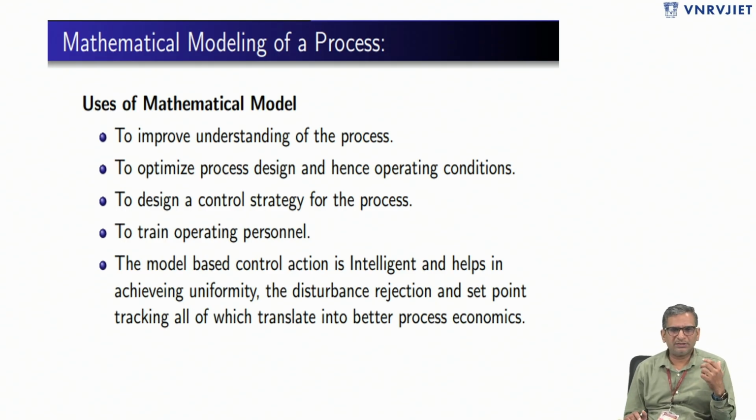In addition to that, once I have a mathematical model, I can use it for simulation purposes, and through simulation studies we can understand the plant behavior. We can use this simulation technique to train the operators. We can understand the plant behavior under different operating conditions by applying various inputs or stimuli, like standard test signals: ramp, parabolic, step inputs.